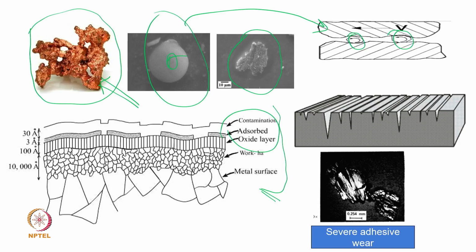That will give a good indication. If I get a completely virgin, fresh surface, that means something is wrong, the system is not behaving correctly, it is not getting oxide sufficiently or not getting lubricant sufficiently, and we need to work on it. So, even looking at and analyzing the wear debris or fractured wear debris will provide a lot